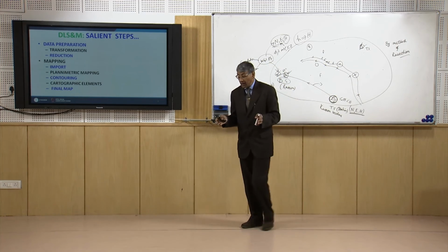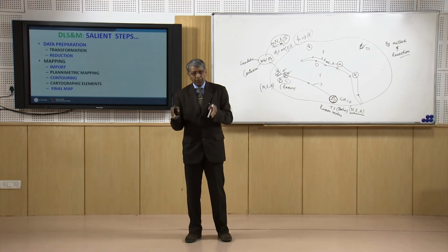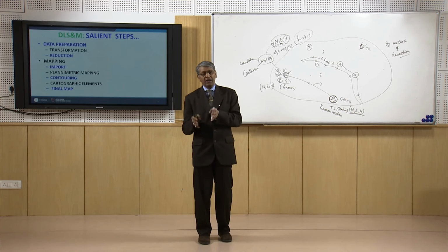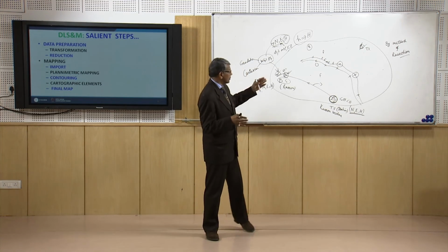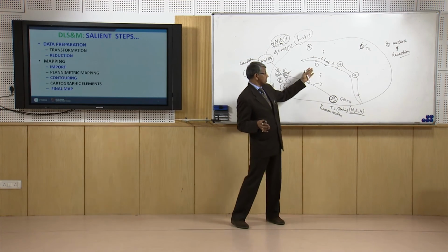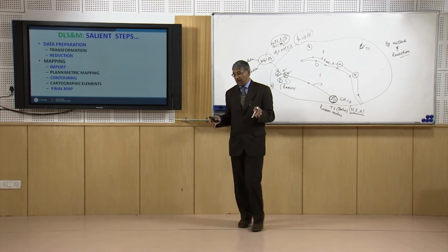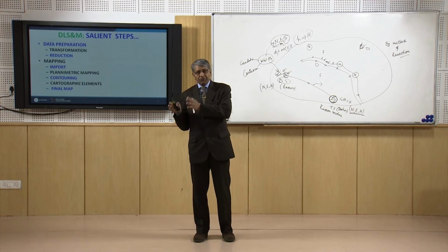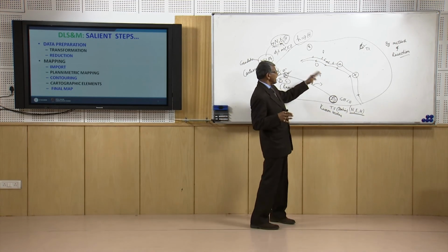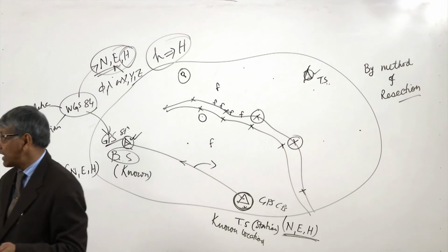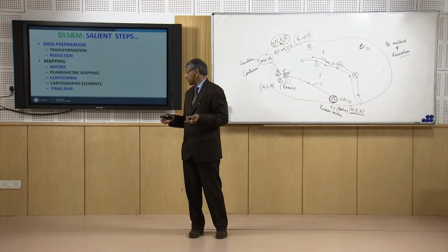We can make use of the interpolation technique which we find suitable for our work, and we can do the contouring. Sometimes we can test whether our contouring really represents the field which we want to represent, and sometimes we may need to change the interpolation technique to get the appropriate contours.